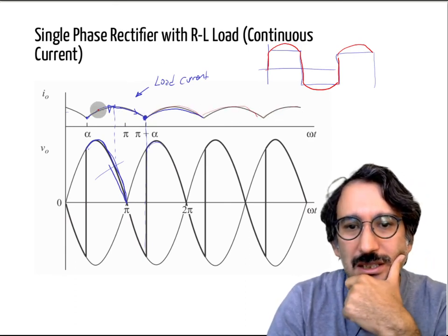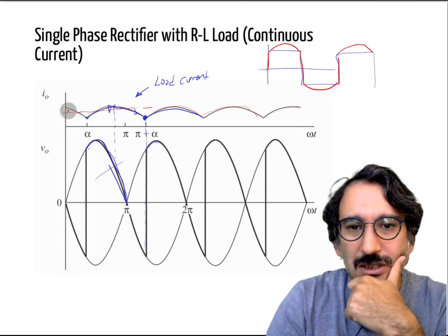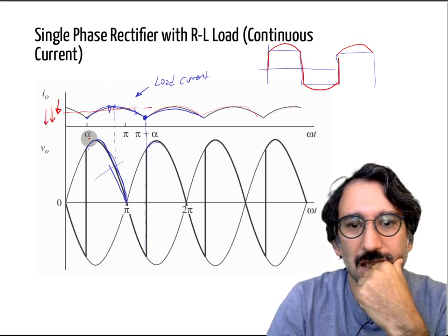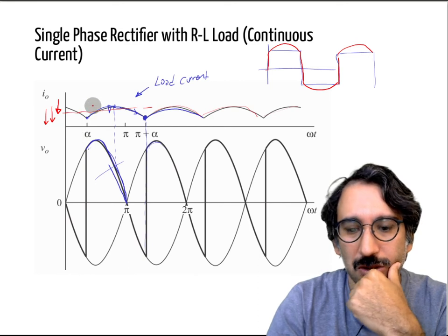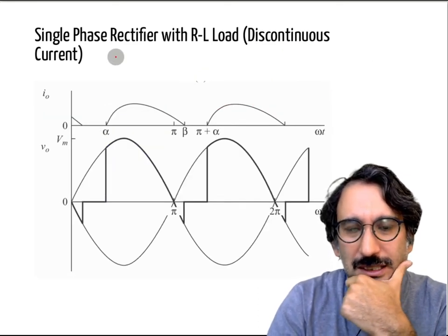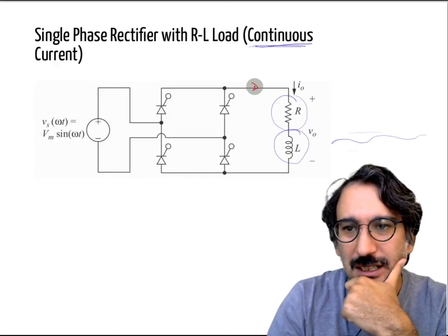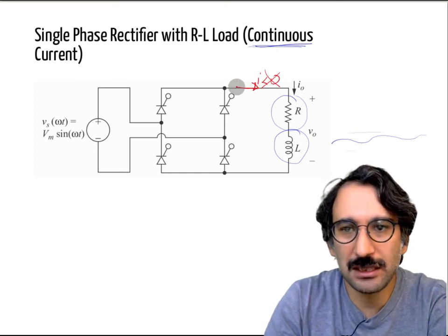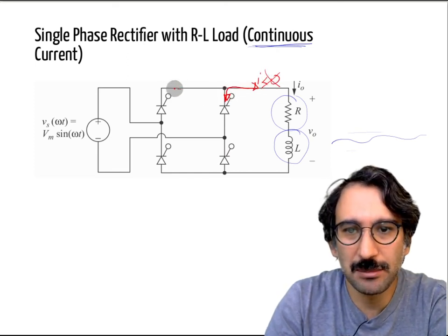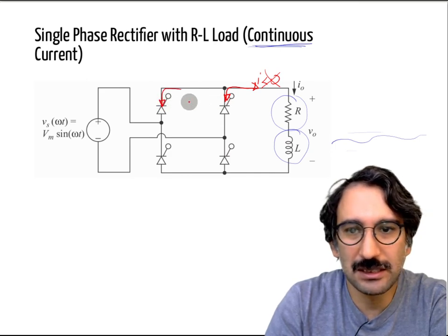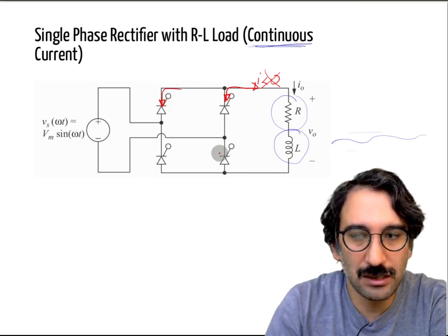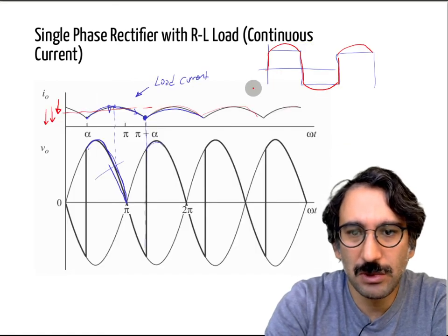So my question is, what happens if your average current is reduced? If that one is reduced and that one is reduced, so it is getting smaller and smaller, right? So then again, the problem is, if you just look at here, that current cannot be less than zero, because that implies some current to flow either that path or that path, but it is not possible, as those are thyristors. Okay, so what will happen?